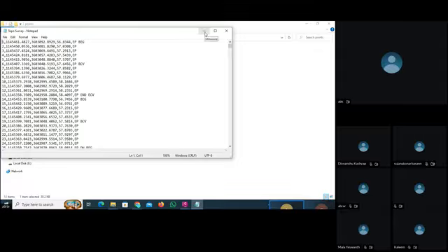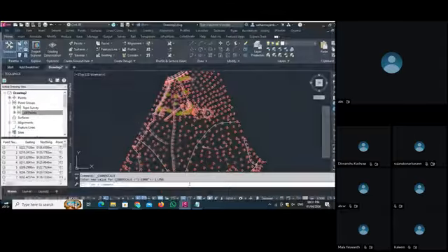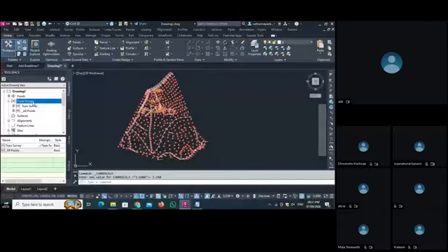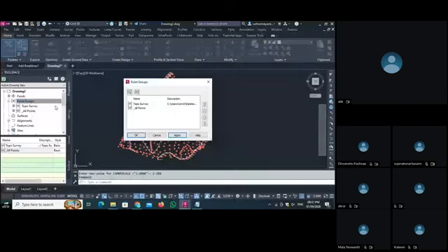Okay, so now what we do first, we go here where we import our points, and let's create our first group. You have to come here in the point groups, then right click here, then first check the properties. In the properties, you can see we have two groups here. As we inserted groups below the point groups, you can see all the groups here from the properties.